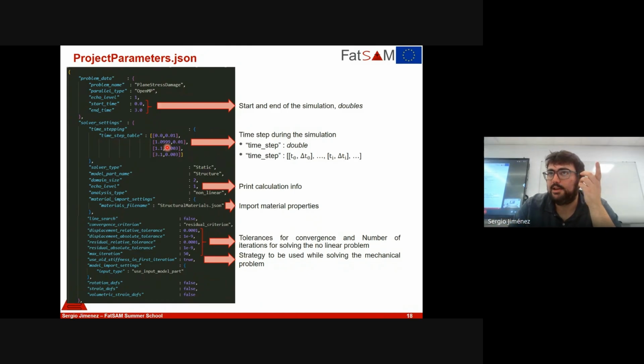If you have a look at the constitutive laws in the H files, at the bottom of the H files there is a block named serialize or something like this, containing the various member variables of each of the constitutive laws, and this information is then used for restarting purposes. Okay, so yeah, it is available, but I'm not sure which is the exact process to activate it, because you need to store quite a lot of information from the previous steps.